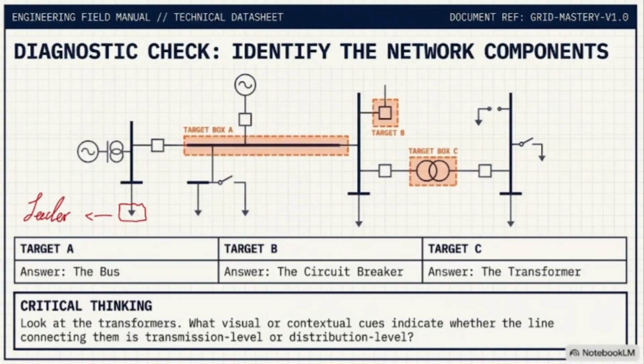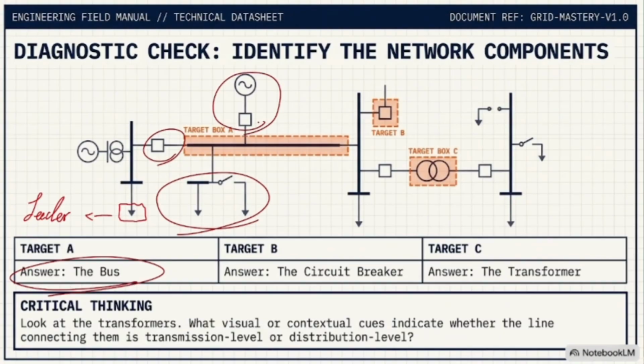When we are talking about the SLD, it's very important to know the symbols. The very first important symbol is something that we call a bus or bus bar. What is a bus bar? Bus is the place that all of your components are going to be connected to. Imagine that I have some components, yet we don't know what they are. This part is going to be called a feeder, or the feeder is going to be a load, and then we do have another component. All of these components should be connected to a point. The point of interconnection of all of these components is something that we call a bus.